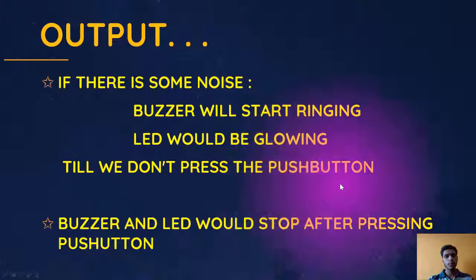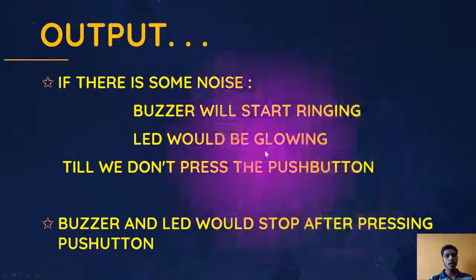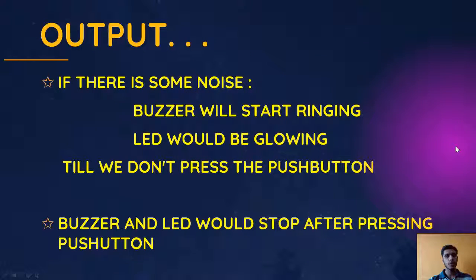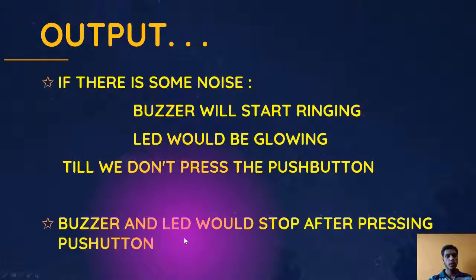When we press the push button, all the signals would be reset and the JK flip flop would be in the reset condition, and the buzzer would stop ringing and the LED would be off. Buzzer and LED would stop after pressing the push button.